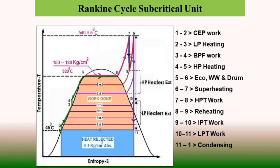This way a number of extractions take place from the various stages of the turbine, and all these extractions add heat in the regenerative feed water heating system, thereby improving the cycle efficiency. At the same time, we keep a balance of expansion in the turbine so that we can also get sufficient useful work to generate power in the system.